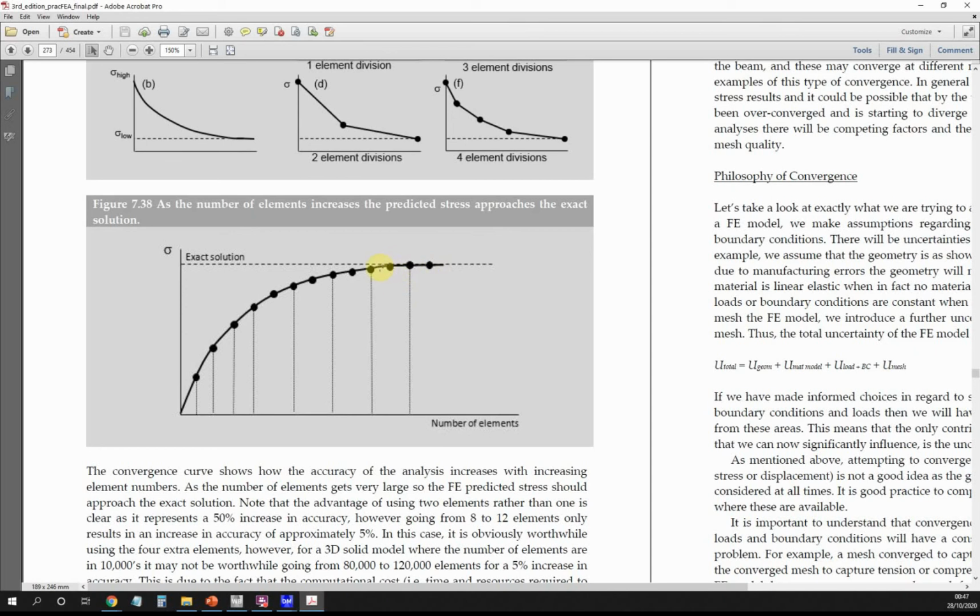Once we've done that with our finite element model, that means we can have reasonable confidence in the mesh. Normally it's very good to have an exact solution to converge that to, so like an experimental result or something like that. Here the best we had was stress concentration factor, which again is quite limited. It is simple theory.